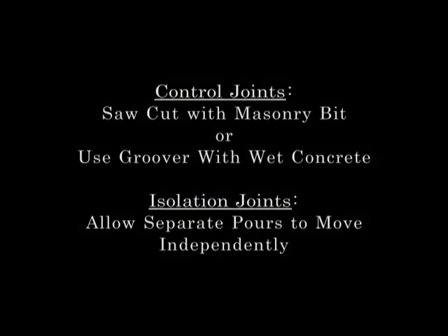Concrete slabs have a tendency to crack, and there's not much you can do about stopping that. We use the welded wire mesh in there to stop those cracks from opening deeper once they've occurred. You can also use fiber down in the concrete when you pour it, which will help stop those cracks from starting initially. But basically, you're going to get cracks one way or another.